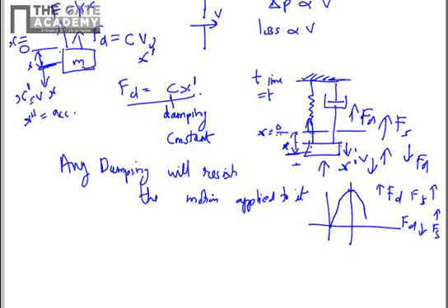The only thing you have to keep in mind is that you take the displacement from the mean position, and opposite to that direction will be the spring force, and you take velocity at any time instance, and the opposite direction of the velocity will be the damping force. So with this we have outlined a framework for our derivation. Now we will go on to the analytical derivation of free force and damped vibration of the system.